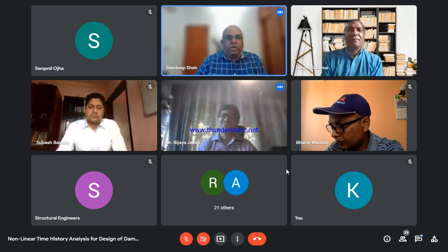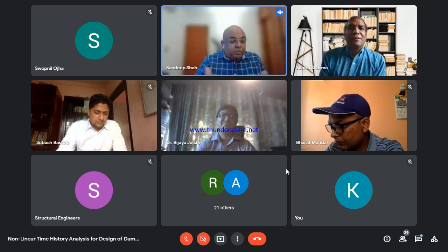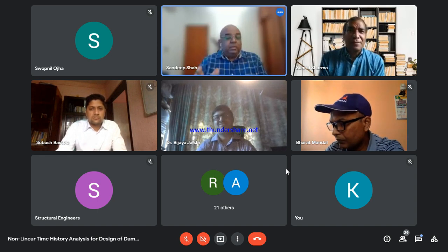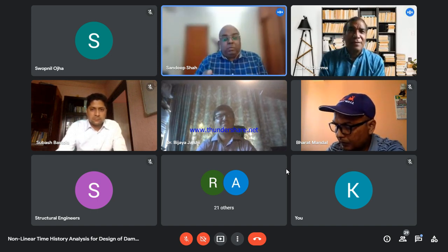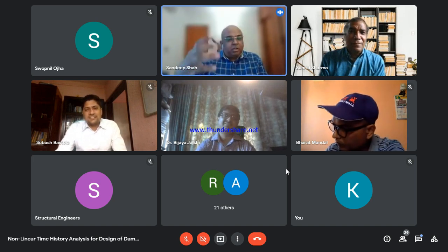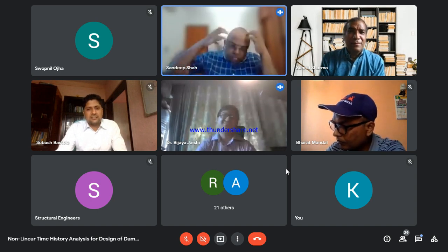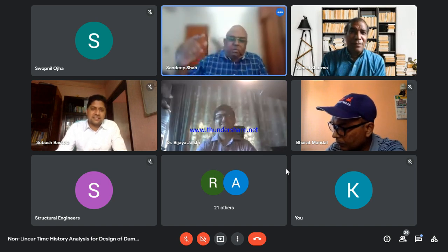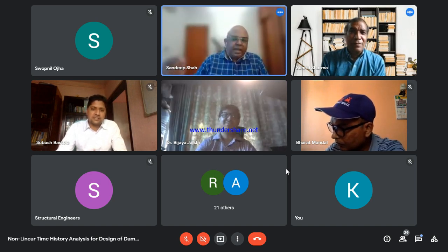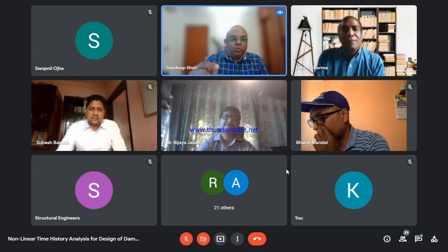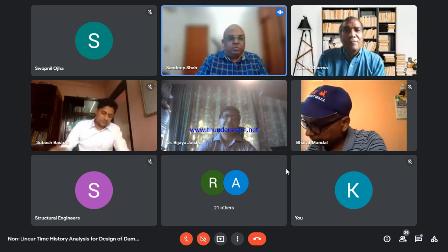So you can calculate in percentage terms. Now again, structural engineers, this is a very nice question you asked, actually. The way our mind works, we only calculate the structural cost, right? So let's say the structural cost is 2,000 rupees a square foot. Now, in all my slides I gave very specific values: keep the floor accelerations less than 0.2 g, and your non-structural components will get protected.